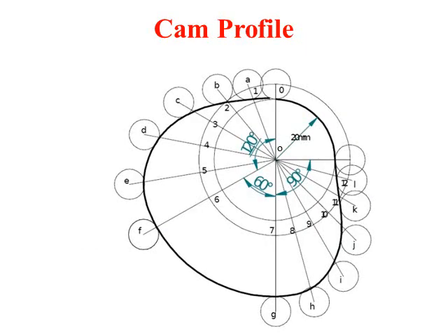After this, we need to draw the cam profile. So the cam profile will be in line. Initially we need to draw the base circle of the value mentioned. Now, as I discussed earlier, this is a roller follower. We need to draw the prime circle, and remember, the prime circle will always be greater than the base circle.